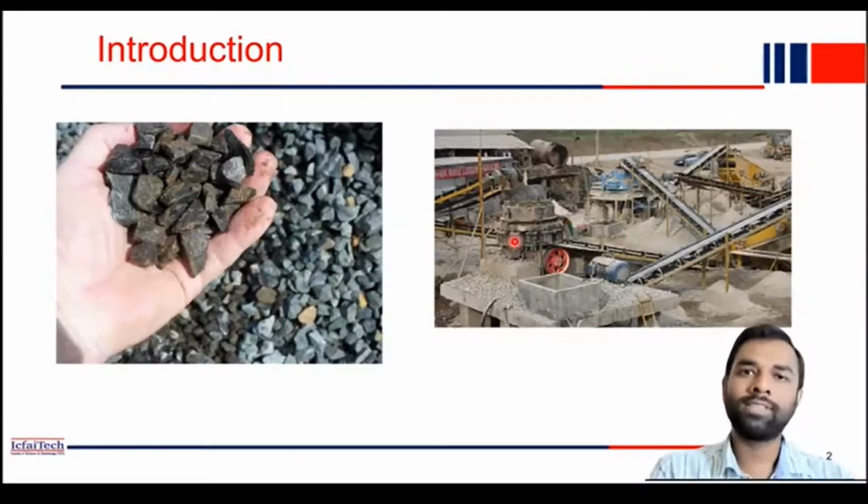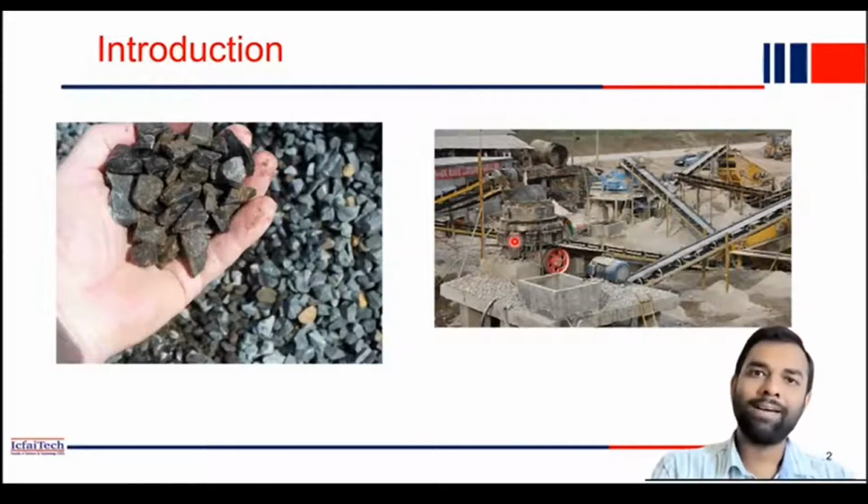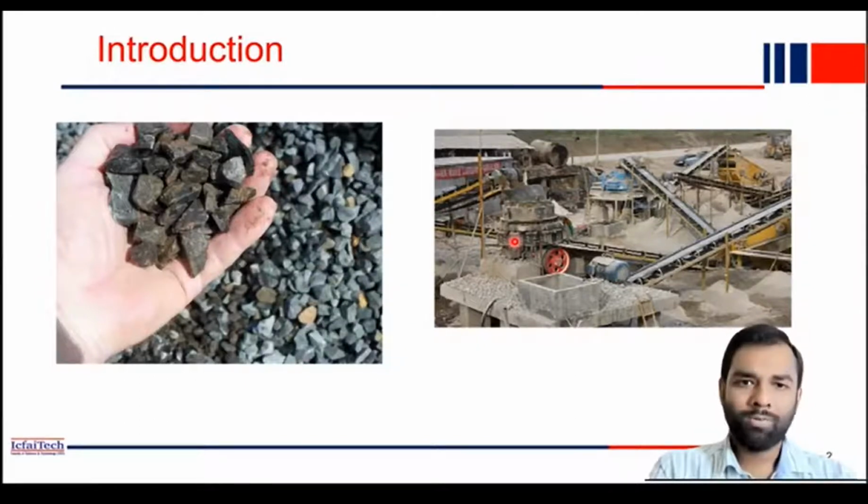Even for road construction, when we make our subgrade soil, that time we use bigger dimensions of aggregate, right? But when we construct the slabs or the beams, columns, that time we use lesser dimensions, maybe 20 mm diameter or 12 mm diameter size of aggregates, right? So while crushing the aggregate, we have to get the proper size of aggregate, which is required in our construction purpose, that only we should make, right?